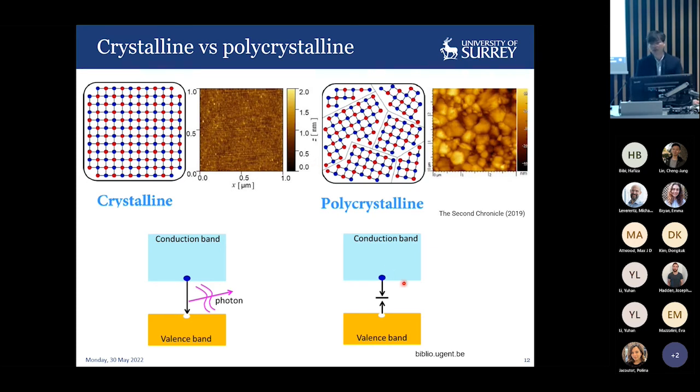And in many electronic materials, grain boundaries are found to be a defective area that promotes non-radiative recombination. And what we mean by non-radiative recombination is that we have a trap level that exists in between the band gap, and when excess carriers are generated, they get trapped and recombine in that energy level. So we sort of waste our carriers rather than having a valence to conduction band to band generation. So that's found to be very harmful in terms of electronic properties. So that's why people, especially in silicon, try to move on to monocrystalline silicon.